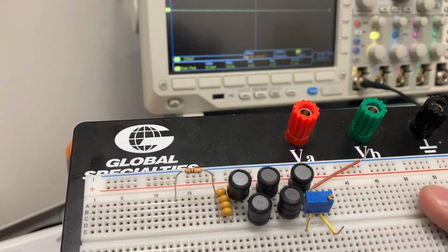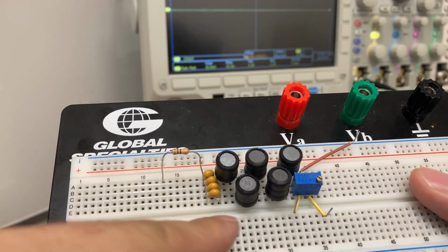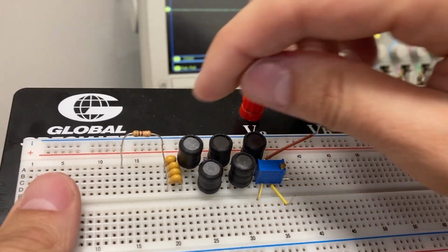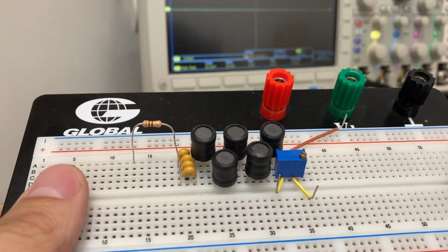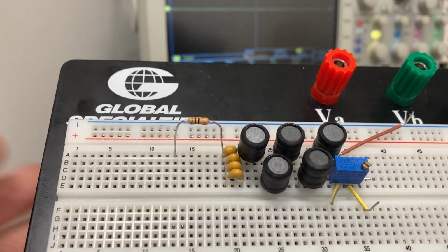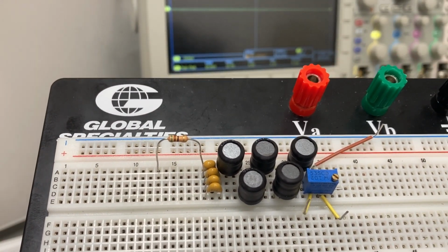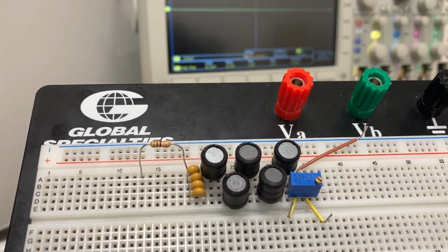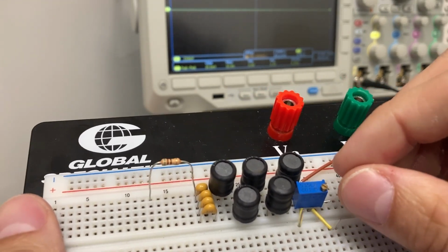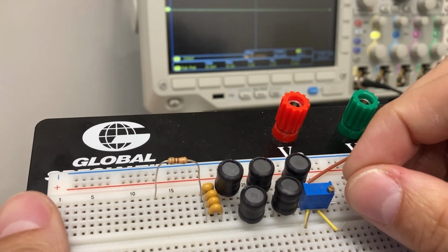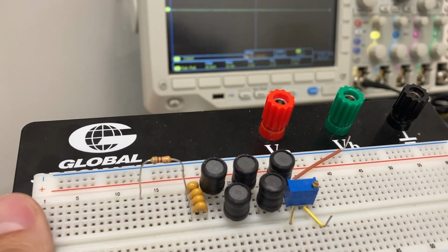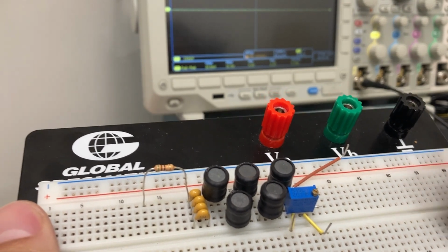For the inductors, I wanted 4.78 millihenry, and actually I got that just about on the dot. But one important thing here to note is that all of these added inductors also increase the resistance of my circuit. So I measured that on the LCR meter, and I had an additional resistance of 9.5 ohms from these inductors, right? So it's a couple things here to think about. When I do a measurement, I basically always have to bear in mind that it's whatever I measure plus the value of the resistance from the inductors. But initially I'm going to ignore that.